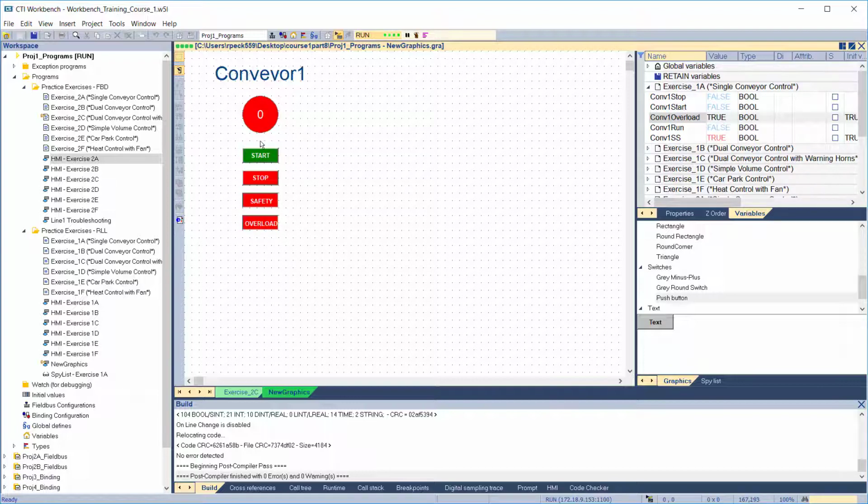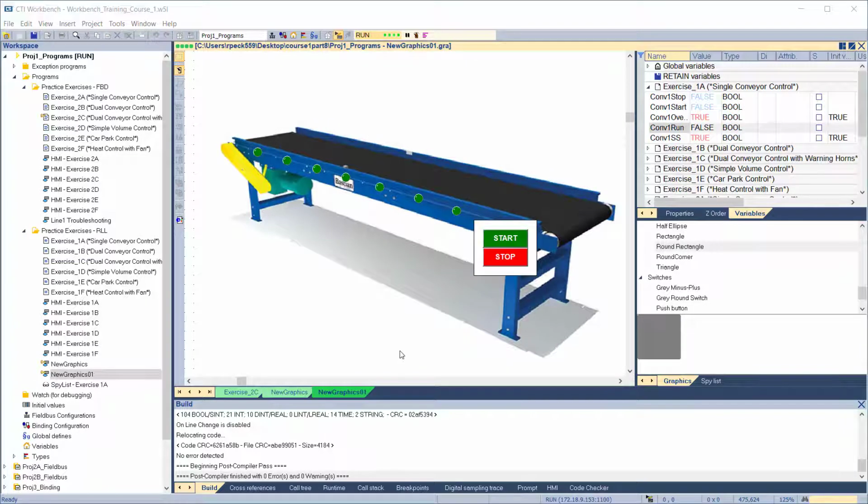Also working. As you can see, building a simple graphical display makes it easier to test the project, compared to manually setting variables. With a little more time spent in drawing and configuring the diagram, you can make graphical displays equivalent to basic HMI devices. Here's an example using an imported bitmap of a conveyor, with controls and indicators overlaid.